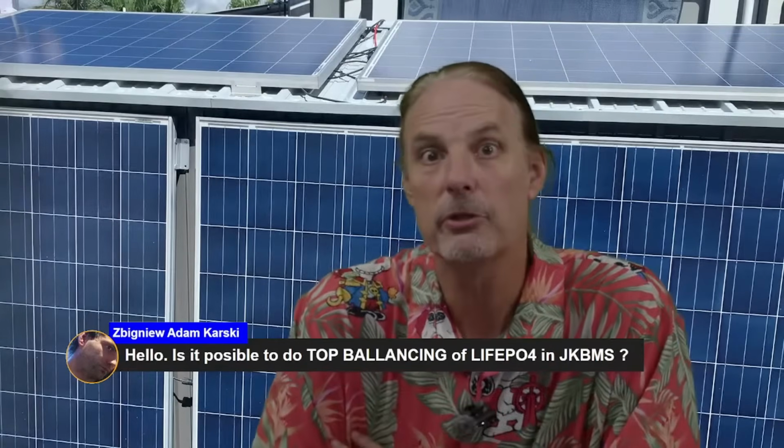I don't know that I have a video out on it yet, but oh, actually I do. The battery building video that I put out earlier this week, the DIY battery, does go into the JK BMS and how it's configured. But basically you're looking at setting the cell minimum voltage for it to start, which in my case is 3.4 volts.